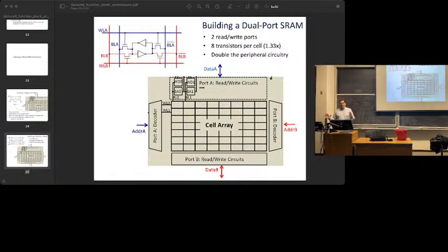Because a processor, it's the centralized memory issue in processors. You build a register file, you hook all your functional units to it, and you've got a whole bunch of functional units. Turns out you now need a whole bunch of ports. So the SRAMs that form register files in processors are highly multi-ported, and that makes them bigger. It also starts to slow them down some, right? So there's some cost to that.